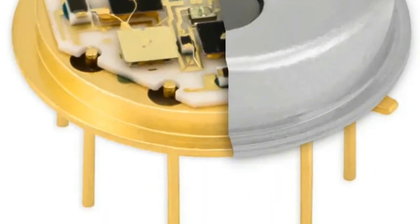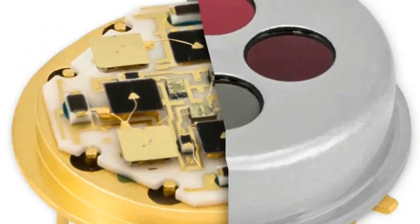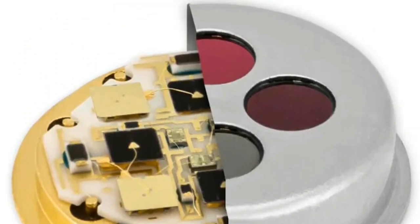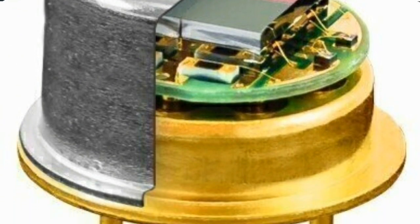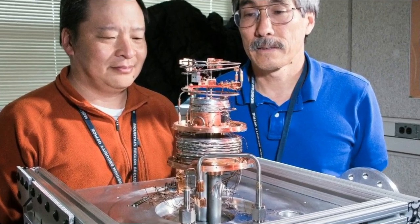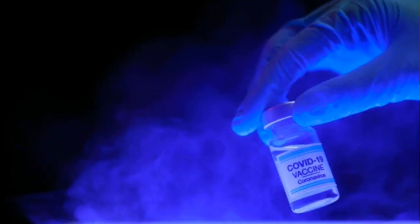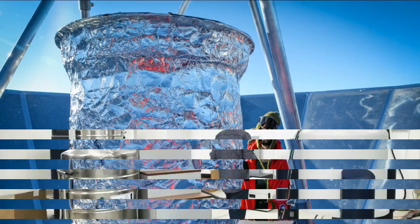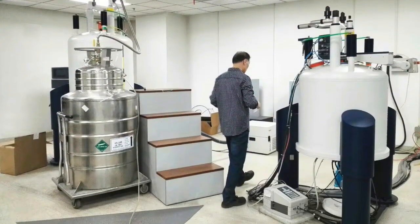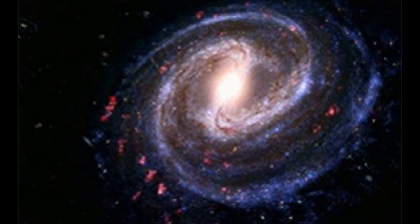The signal output of a quantum detector, typically a gallium arsenide (GaAs) semiconductor chip, is very small and easily swamped by noise generated internally to the sensing device at room temperatures. To overcome this problem, quantum sensors are often operated at cryogenic temperatures such as 77 K liquid nitrogen or 4 K liquid helium to minimize the noise. This significantly increases their cost. Consequently, they are only used if high sensitivity, high resolution, and/or short response times are required at a specific wavelength.